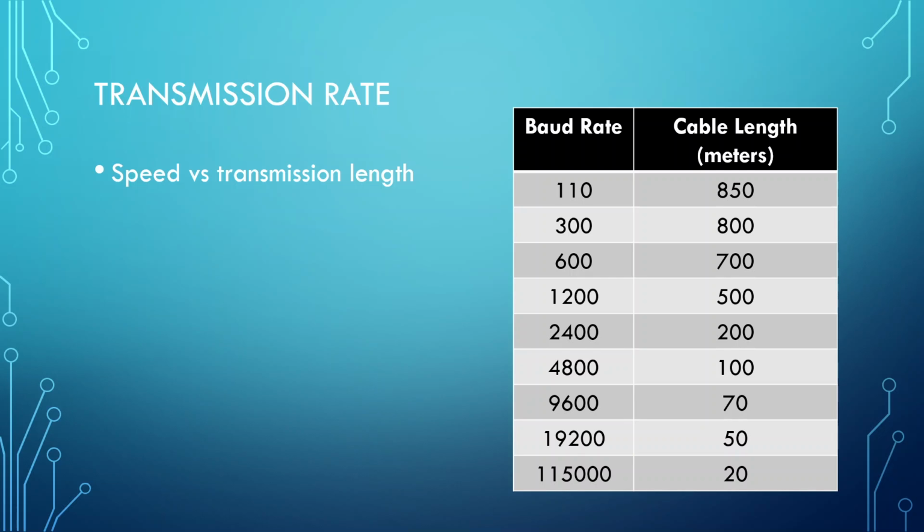Say you're setting up a barcode scanner on an assembly line so you can make sure whatever product is whatever product. That barcode scanner died one day. He went, all right, let me go to the stock room, grab the new one, plug it in, we'll be fine. And then you're like, this damn thing ain't working right. Well, one of the things that you might have to set is the baud rate. How fast am I talking to you?